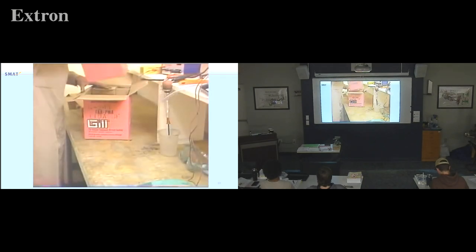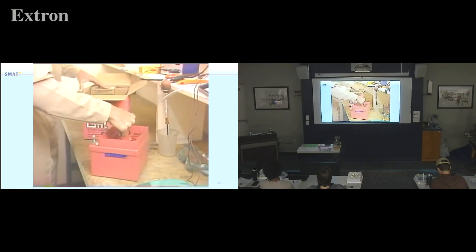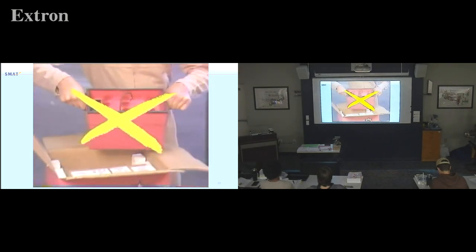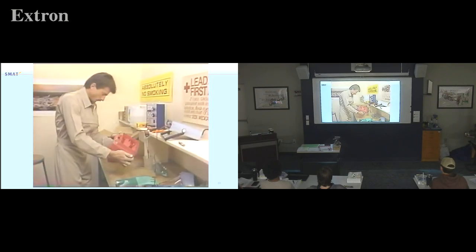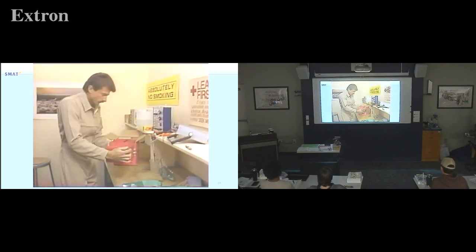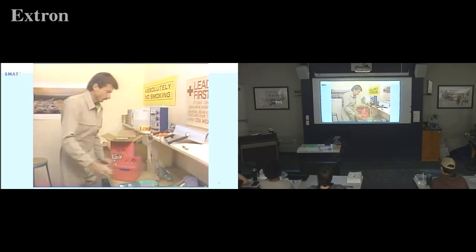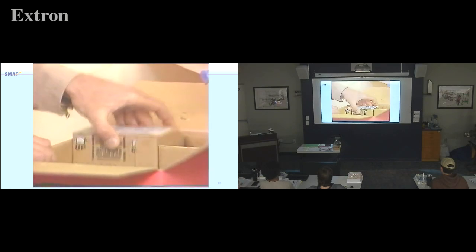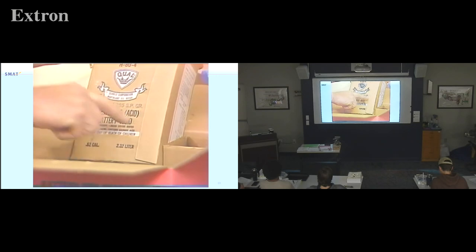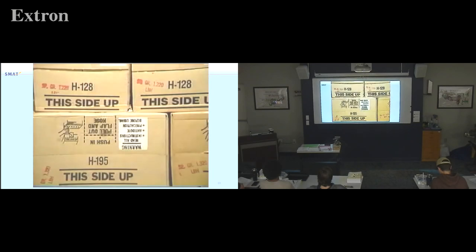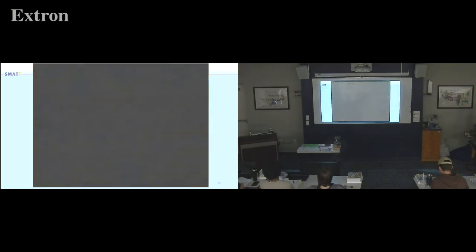Unpack the battery. Use handles or lift the body of the battery. Never lift a Gill battery by its vent tubes or Elcon connector. Inspect the battery to determine that there has been no shipping or handling damage. Make sure that you have the correct electrolyte. That is, electrolyte having a specific gravity of 1285. Electrolytes of other concentrations will seriously reduce the cranking and emergency power of the battery, especially at temperature extremes.